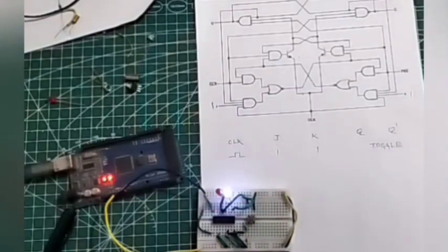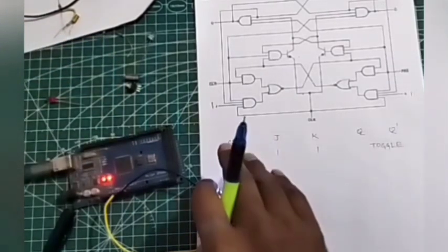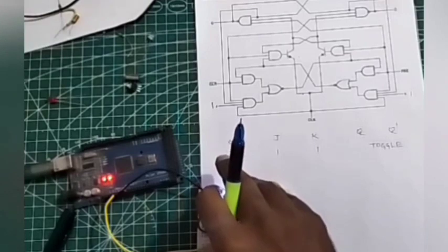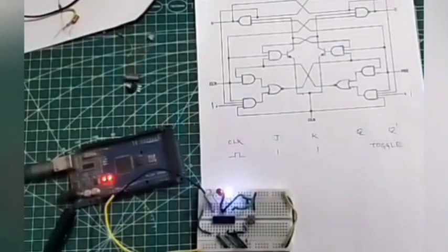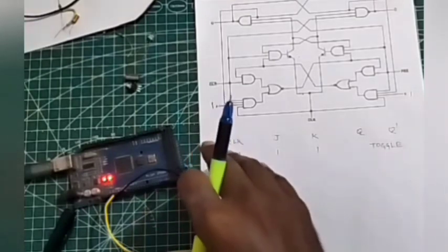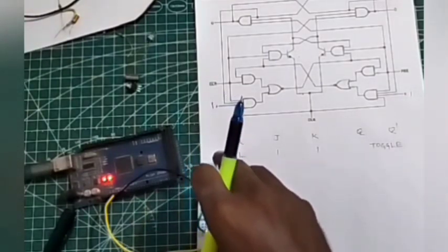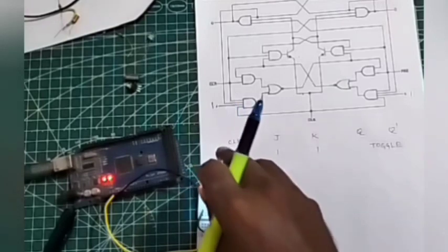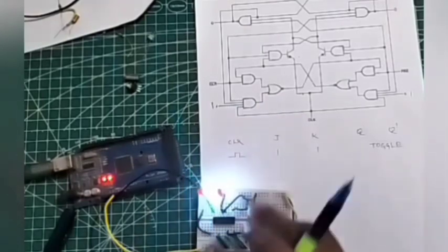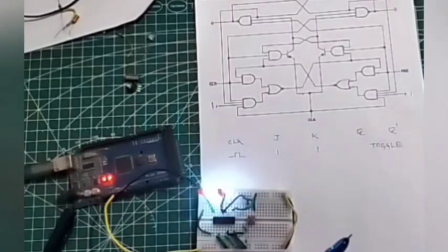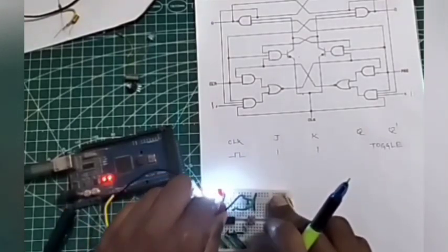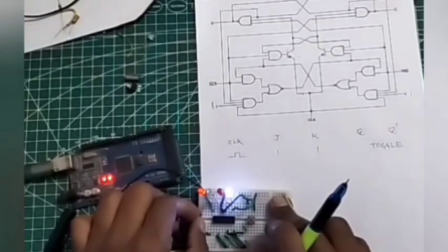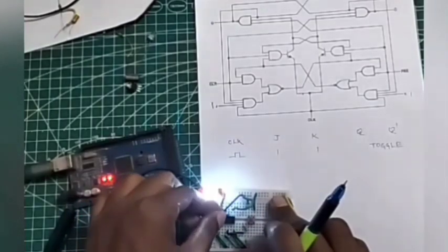Now we are going to add two more in output to this circuit. So this another JK flip-flop will now show something important to you. It will not show unless and until you provide the clock source. So which clock source you have to provide? This one.